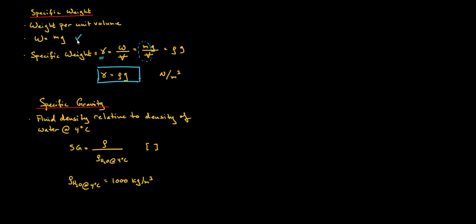And note that the specific gravity does not depend on the system of units employed. So whether we are dividing the densities in imperial units or in SI units, the specific gravity, the ratio of these two densities, will remain the same.